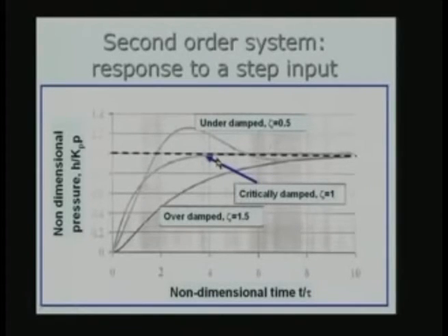Of course, because the system is damped, whether it is underdamped or overdamped, certainly there is damping. In the underdamped case, I have taken zeta equal to 0.5; zeta less than 1 corresponds to the underdamped case. You see that the pressure goes up, the height overshoots and goes to a little more than 1.2, about 25% more. Then it slowly comes down, goes below, and again after 10 time constants it is just about to settle down to the steady state value.